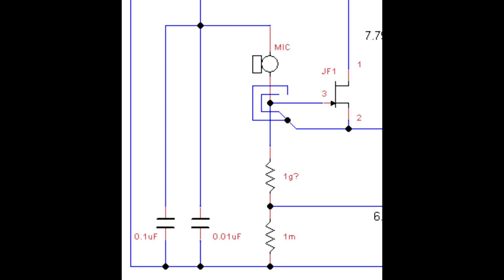So we're charging one of the plates of the microphone to the 73 volts, and it's just sitting there as a DC bias. Now the other side of the capacitor is going to be the part that gives us our signal, the part that we want to amplify. So we send a piece of it over to the JFET. In some circuits, in some manufacturers, you'll see that that point is extremely critical for leakage currents. Sometimes they put it on a Teflon standoff. In this particular design, it's just on the PC board, but they do put some guard traces around it.